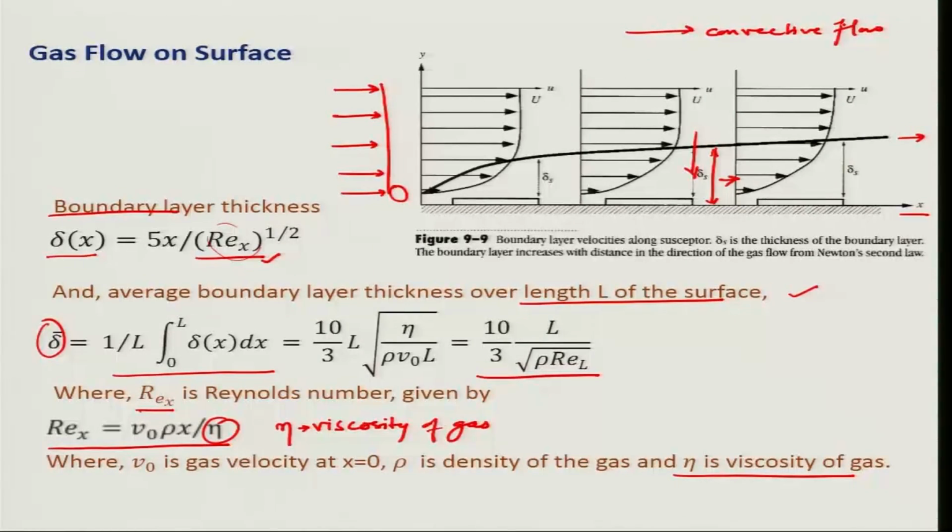One is convective flow in the bulk of the reactor, and the other is diffusion across the boundary layer. Both of these are important for our reactants to reach the surface, where they would react and form the thin film.